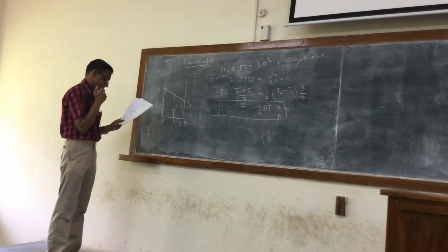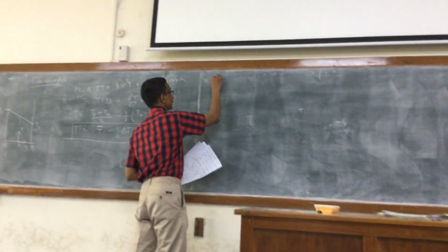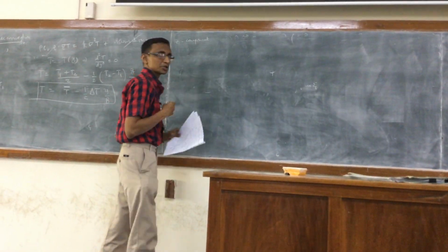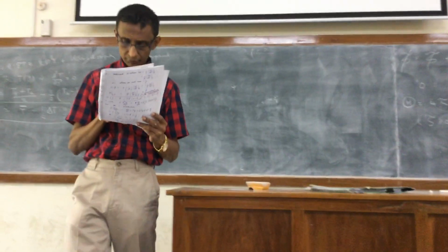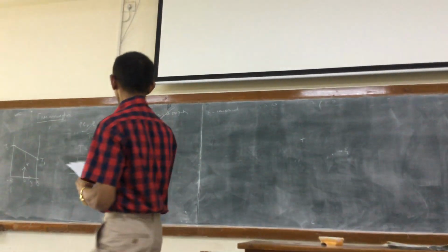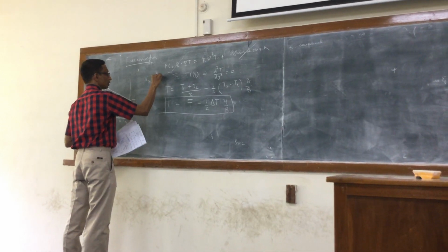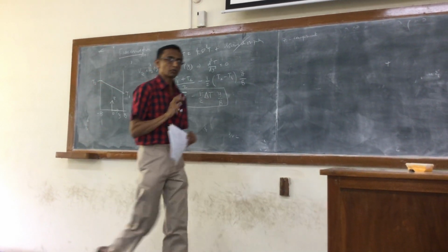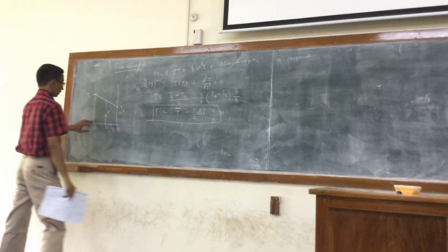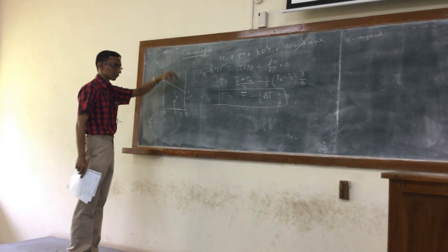If you look at the z component of the momentum balance, the inertial terms you can neglect, they probably all vanish, because Vz is assumed to be a function of y alone. So there is only one-dimensional flow. The fluid here is going to rise, and then, because it is cooled, it is going to come down.